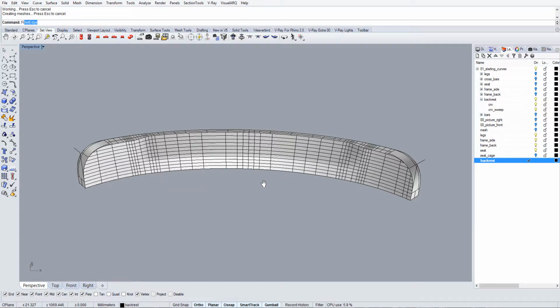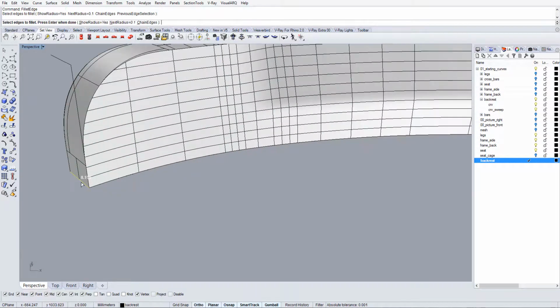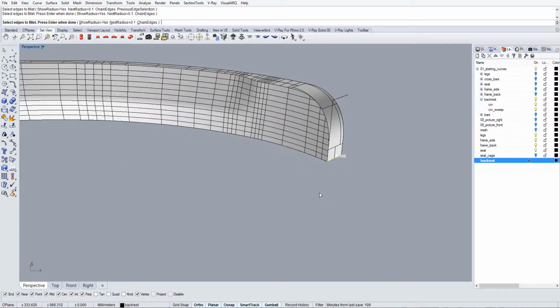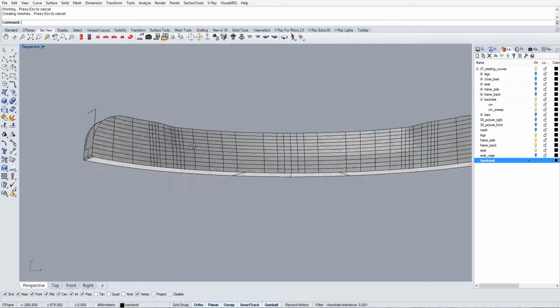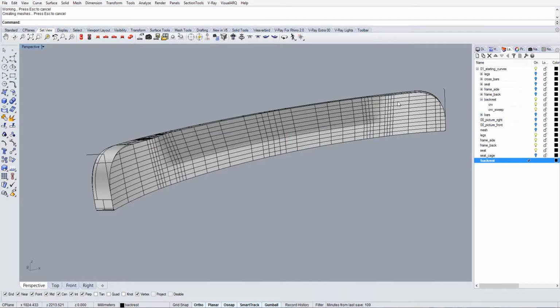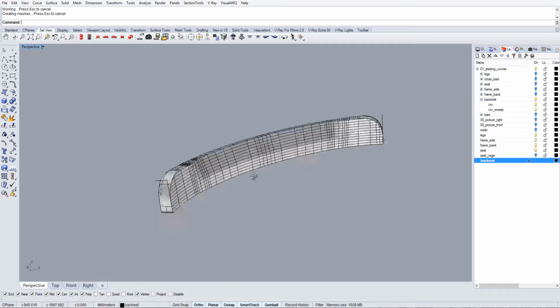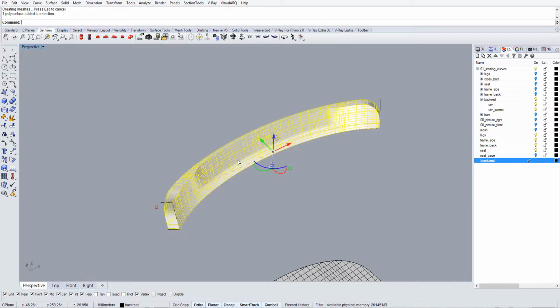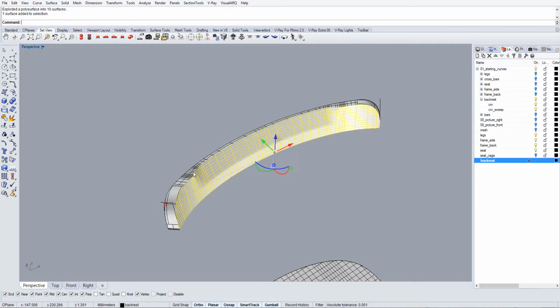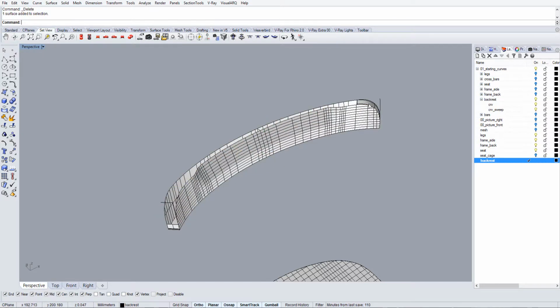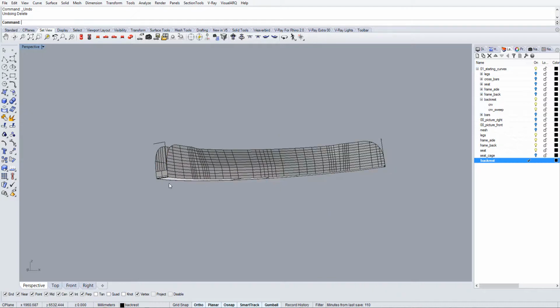And then we're gonna use fillet edge for this one. Oh, and I wanna actually use 2 millimeters for that. Sorry about that. So 2 millimeters. And I want to have the side again only in one piece. So let's explode that. And let's delete these sides.